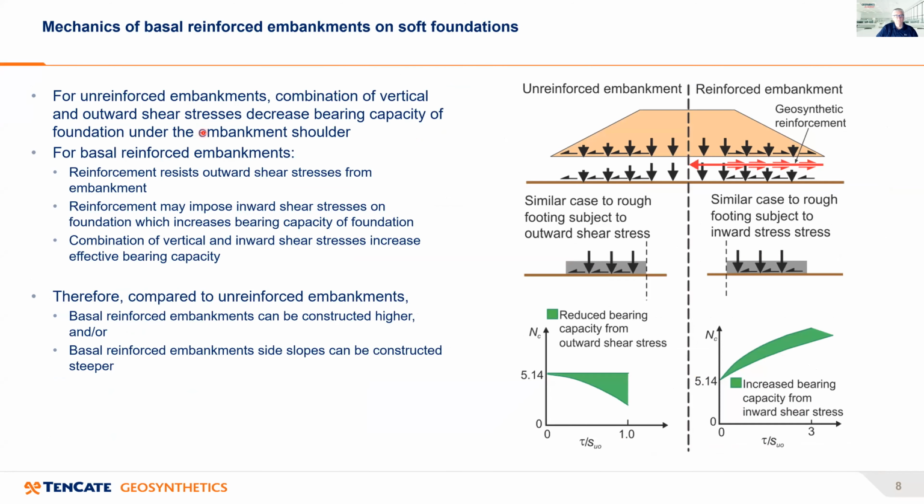So as far as the mechanics of basal reinforced embankments on soft foundations are concerned, I think one way of looking at it is to look at it in a fairly simple way. And a simple way would be, say, we can look at it in terms of bearing capacity theory, where we have the case of the unreinforced embankment, which is shown here on the left-hand side of this diagram, and then the case of the reinforced embankment, which is shown on the right hand. And let's look at what the benefits or the differences are in terms of simple bearing capacity theory.